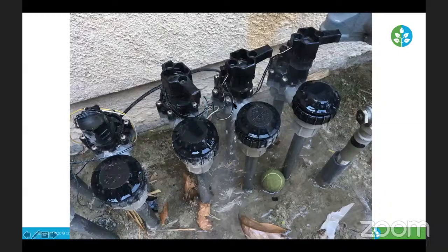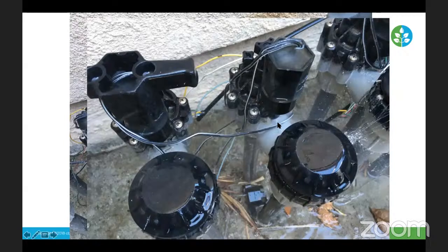So there's a couple options for repairing this. You can buy a diaphragm, but however, the diaphragms do cost quite a bit of money, and certain valves it's best just to replace, unfortunately, than repair. But it is an option of finding those diaphragms. A diaphragm replacement on this valve would fix the issue. So it's just a little bit of a zoomed up picture here. You can see water's coming out right there at the diaphragm, right at the seal.